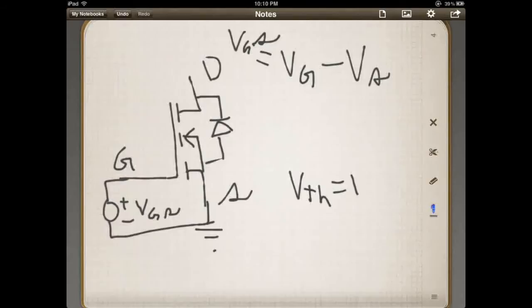Generally speaking, it's about 1.25 volts that you have to go over to put this into what's called the saturation region, which means to fully turn this on where current will flow through it. You have to put about 1.25 volts gate to source on it. You have to go a little bit greater than that to turn this guy on. And that's pretty much it.